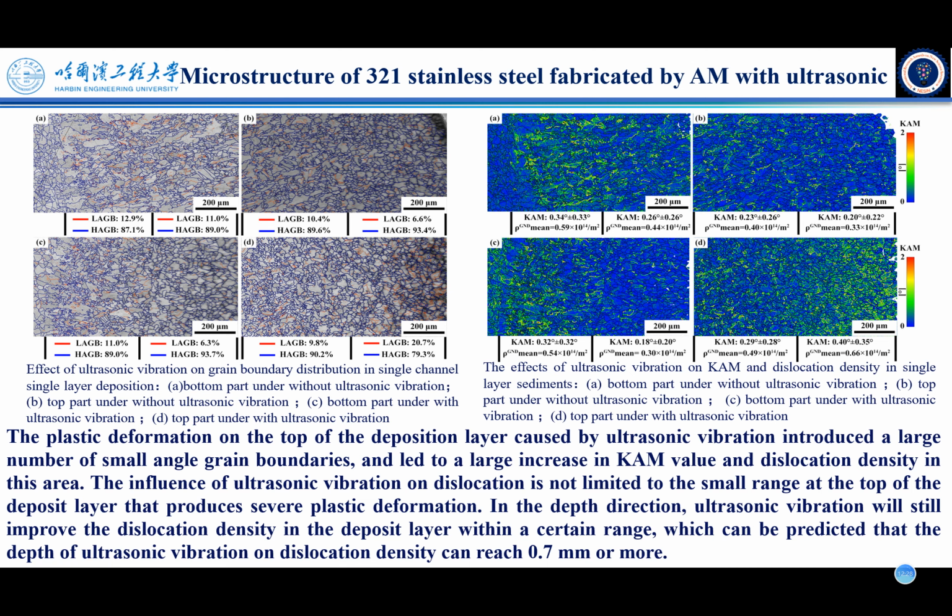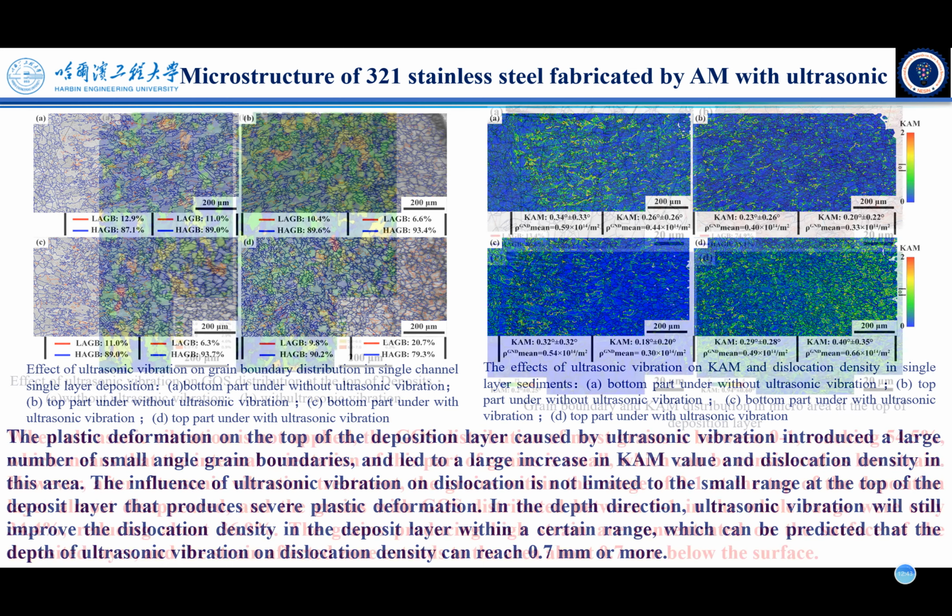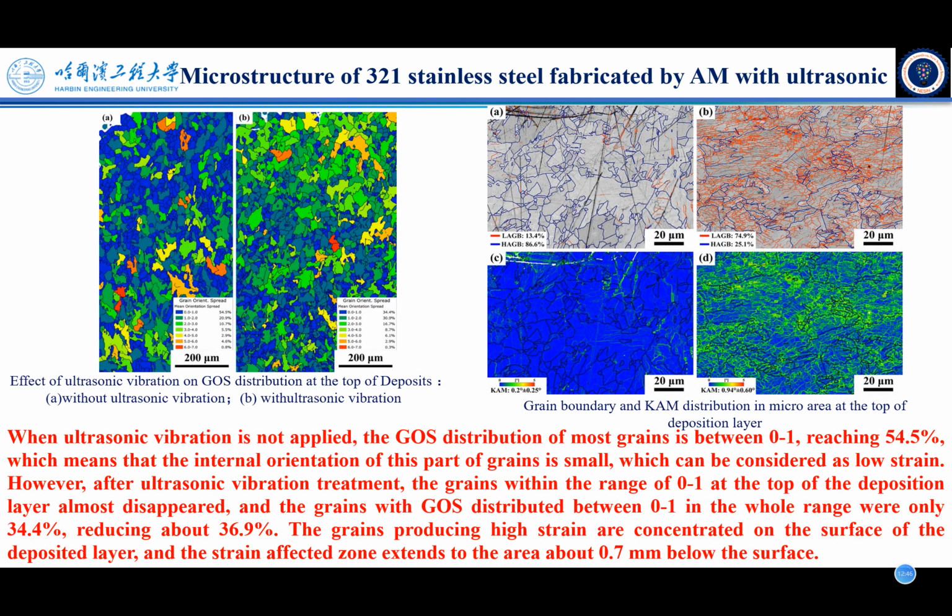In the depth direction, ultrasonic vibration will still improve the dislocation density in the deposit layer within a certain range, and it can be predicted that the depth of ultrasonic vibration's effect on the dislocation density can reach 0.7 millimeter or more.